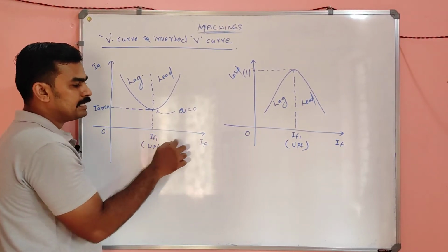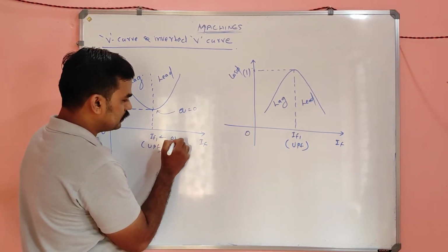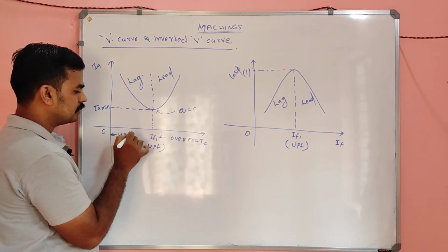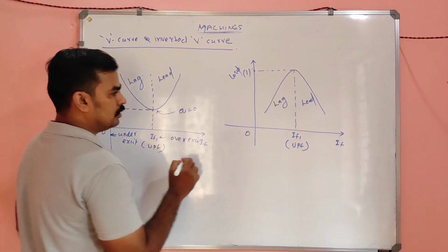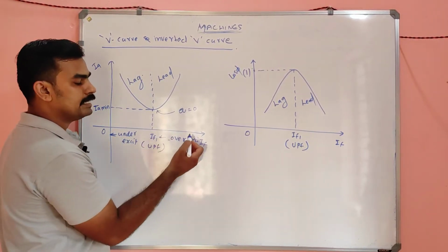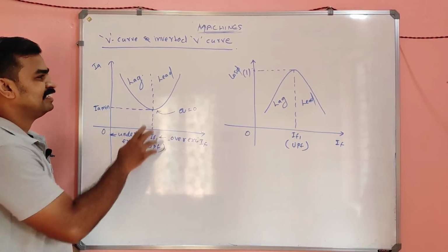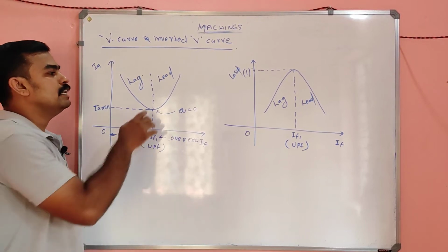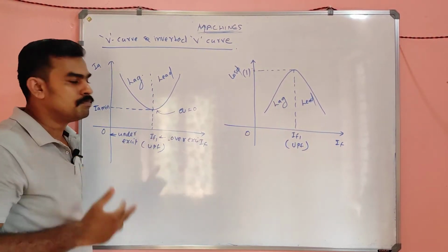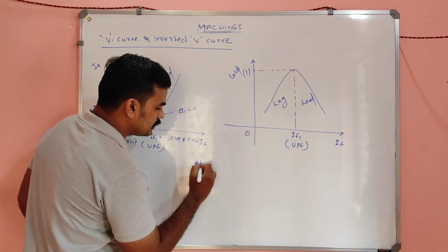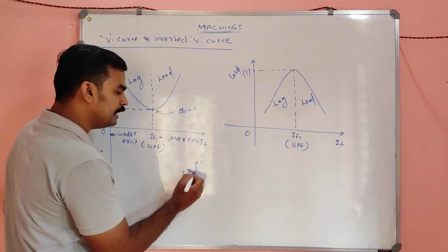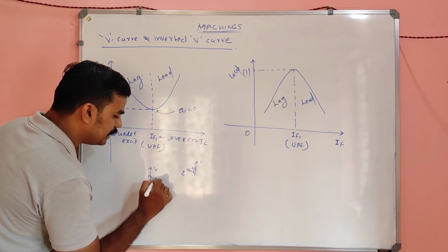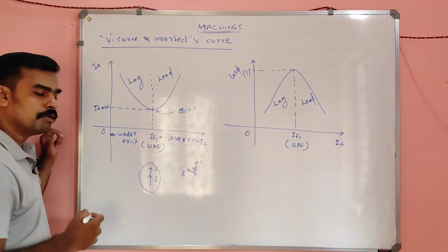If you increase the excitation, this is called the over excitation region, and this is called the under excitation region. Is it clear? So if you increase the excitation from this unity power factor condition, what happens? The machine will lead, which we already discussed. Lead means, my dear, suppose this is the voltage, the current will be leading, that's all, the leading power factor. But we do not need that, we need V and I to be in phase. That is the situation we actually require.